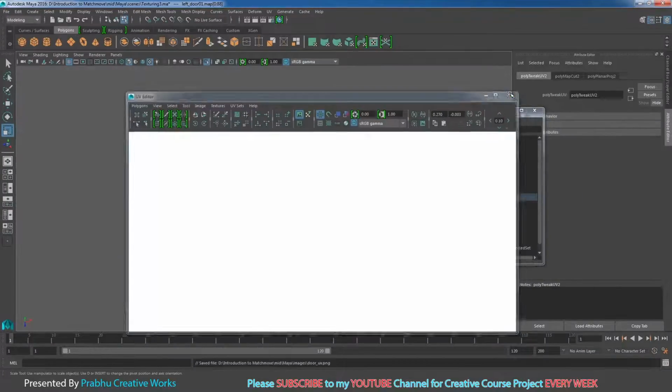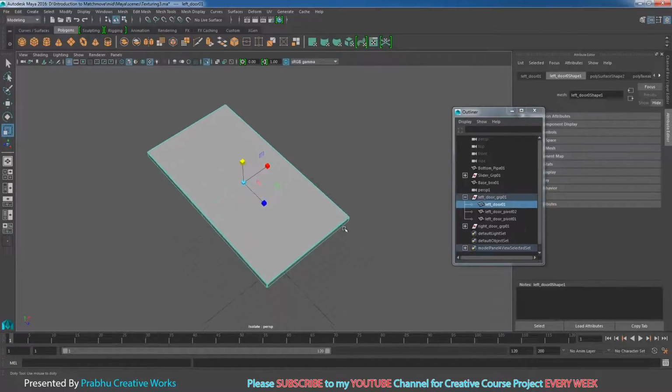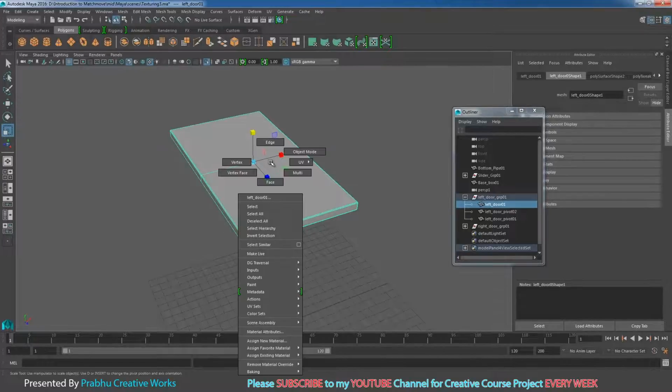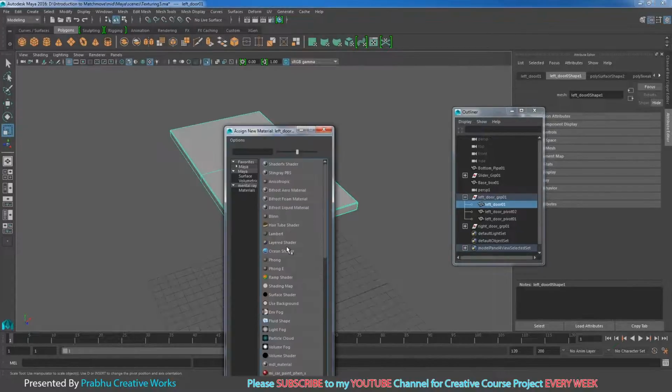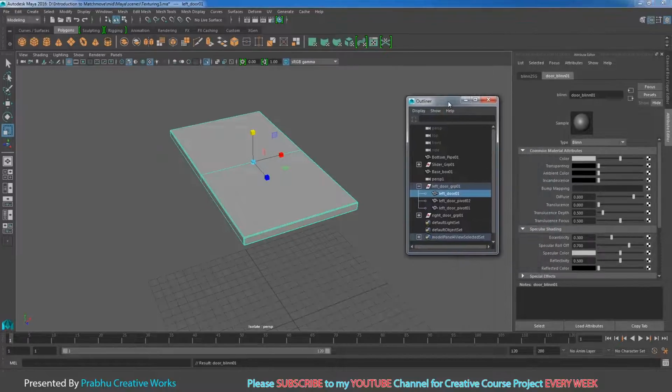So I will close my UV editor. Right click on this object and choose object mode. When the object left door 01 is selected, right click and choose assign new material, and choose blend. Now I want to name this one door_blend01 and press enter. I will move the outliner a little bit.